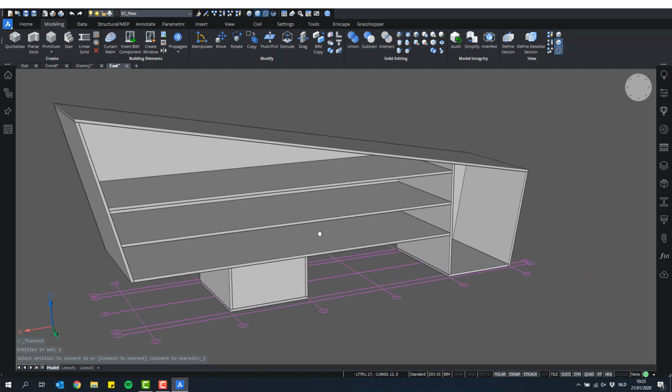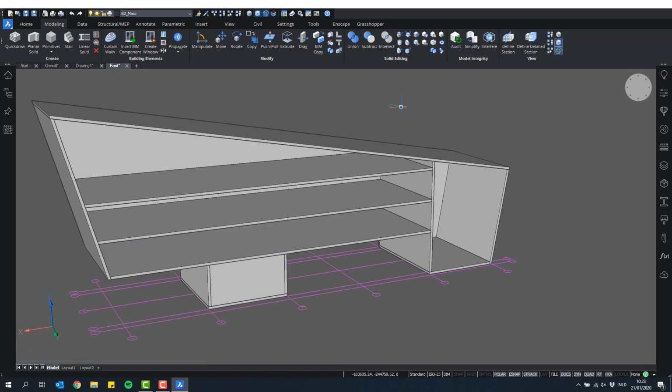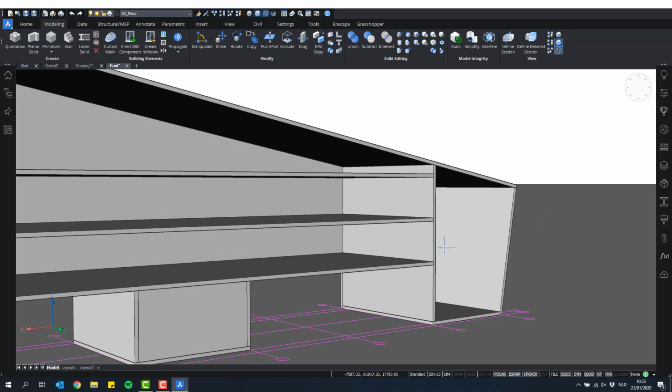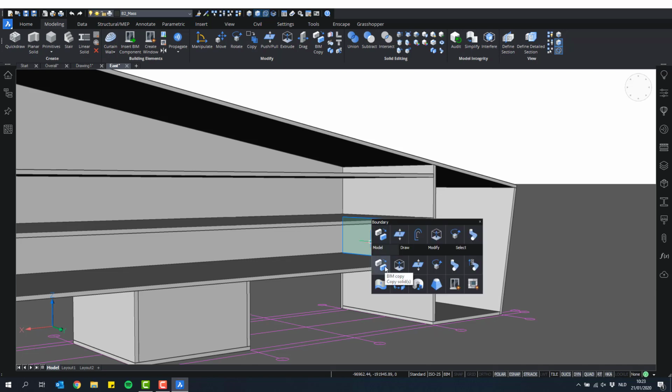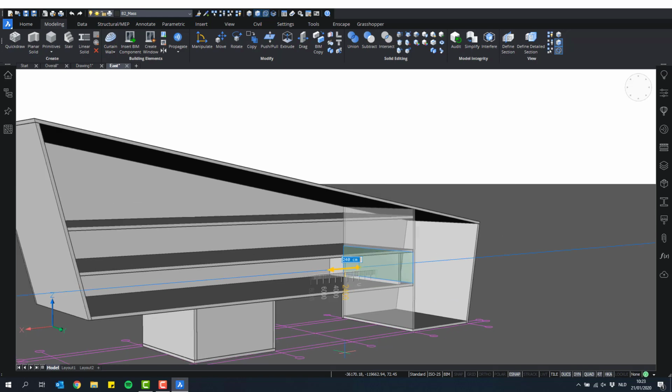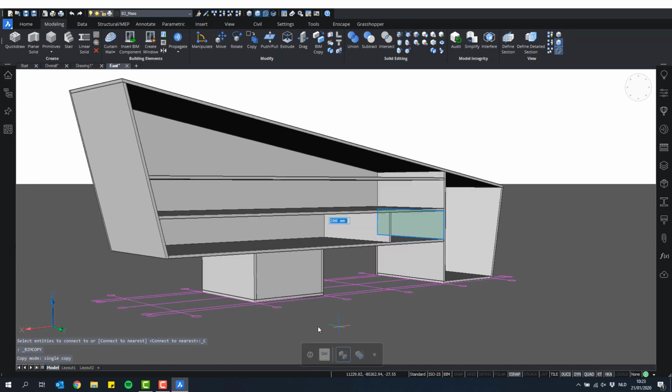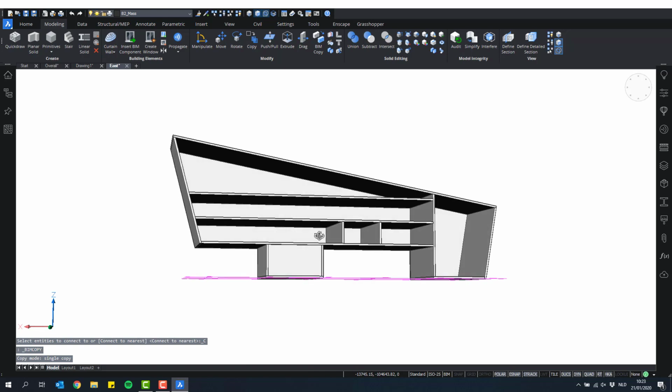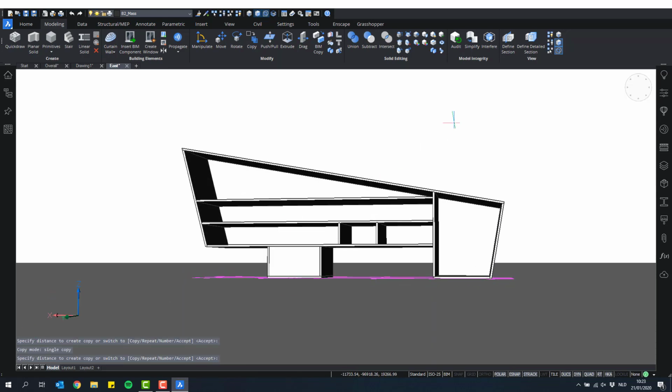As I said, this BIMCopy tool doesn't only work on faces, it also works on boundaries. So if your boundary detection is toggled on, if I now hover my cursor over here, you see actually I don't have this entire face, I just have the boundary between these 2 floor slabs. And you will see in the quad also the BIMCopy tool appear. So I can BIMCopy this section of the wall perpendicular to it, like this for instance. So especially useful to copy sections of walls in a perpendicular situation.